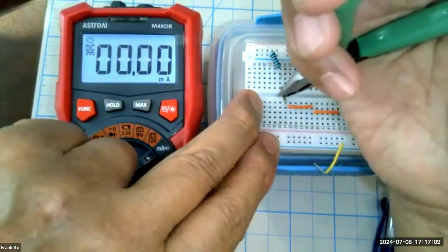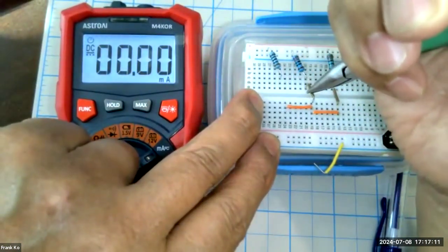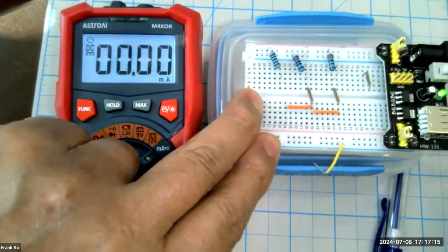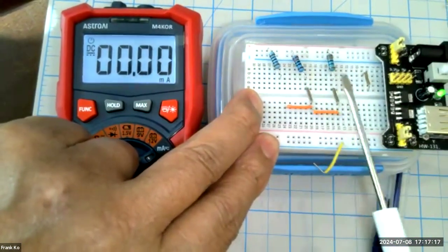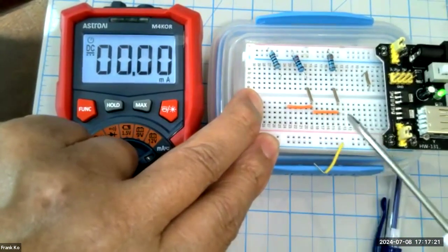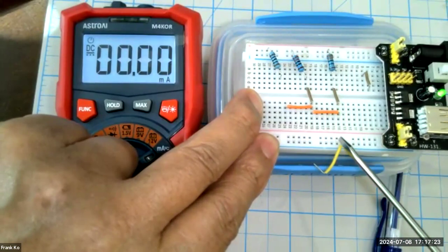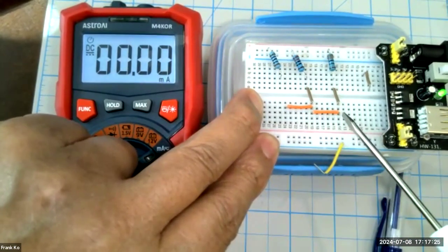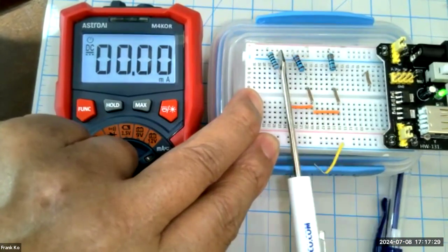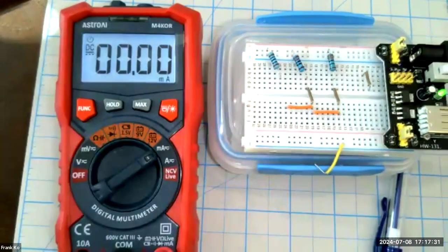Now go ahead and create the fault condition on resistor number 1, branch 1, by moving this jumper here. So we now have two branches that are intact. R2 is in parallel with R3 with one circuit path to ground, and this is where we're going to measure the currents from here to here. Notice R1 is disconnected, is no longer part of the three original parallel resistors.